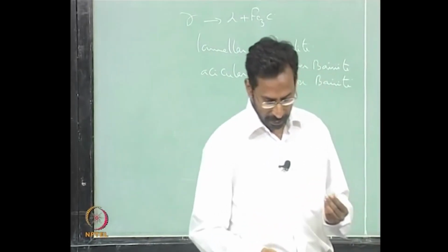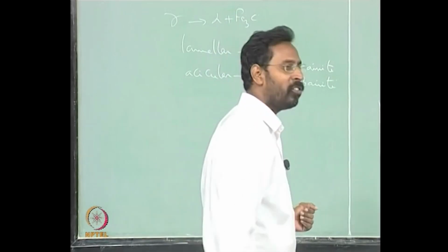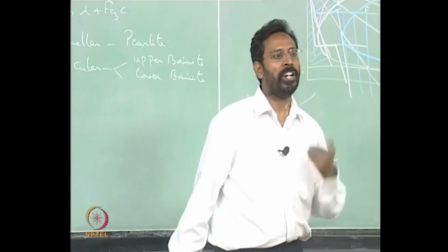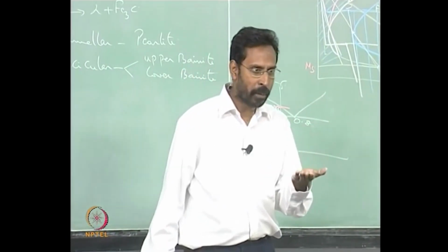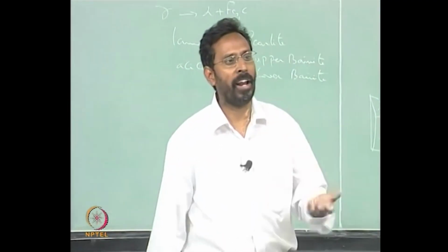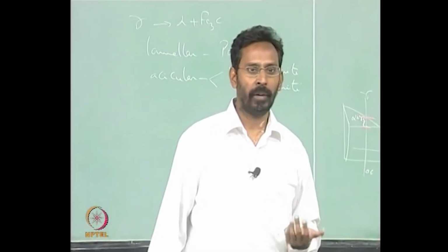Yeah, this is when we come to martensite we will talk about it, okay. There is also always something called deformation induced martensite. The MS temperature can go up. All of us know that MS temperature, whenever you add alloying elements, it always goes down. Why does it go down?